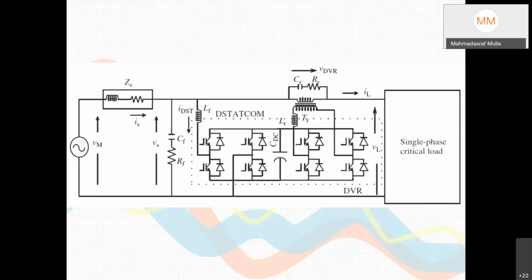Now the current at the receiving end is in phase with the receiving end voltage. So if I still require a further rise of voltage, higher than that amplitude, then not only via reactive power, I require some active power also. Then this UPFC can do that job. So here there is a shunt compensator. We can draw some small amount of active power through this arrangement when both of them are working together, and we can inject through this series.